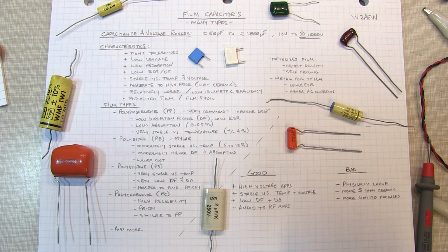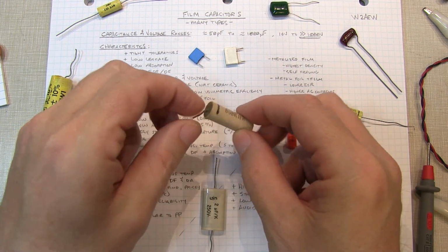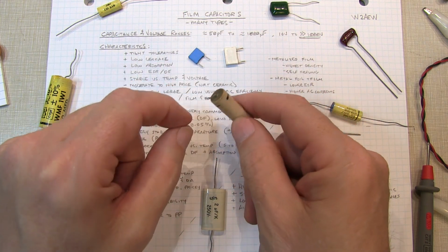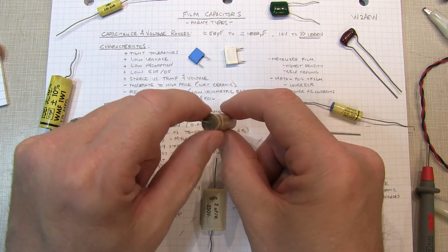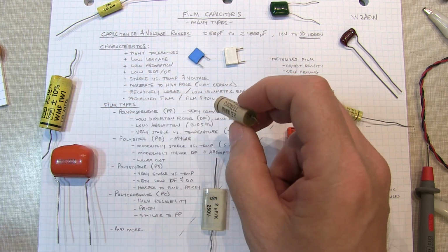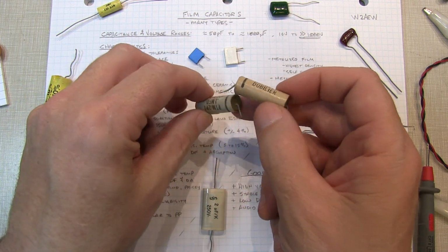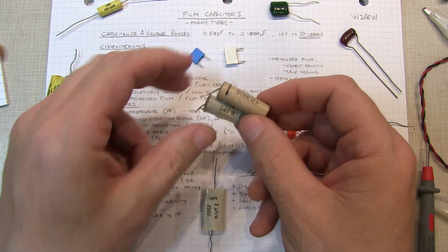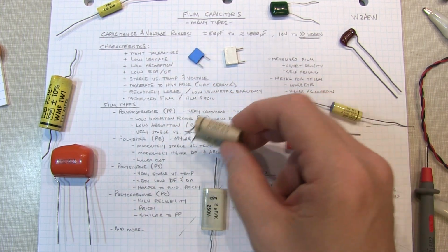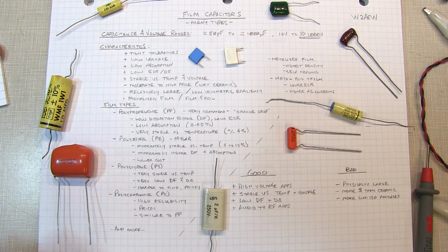These film caps are often the ones that, if you're doing some restoration of old antique radios and things like that, you're going to be replacing. The early ones are old paper and wax, so it wasn't really a film that was the dielectric, it was actually paper that was used. So it was like paper and foil wrapped up and then stuck in the tube and sealed with wax. These capacitors by now are all kind of dried out and leaky and all need to be replaced. And replacing them with mylar or polypropylene caps is the most common thing that you would do in these applications.